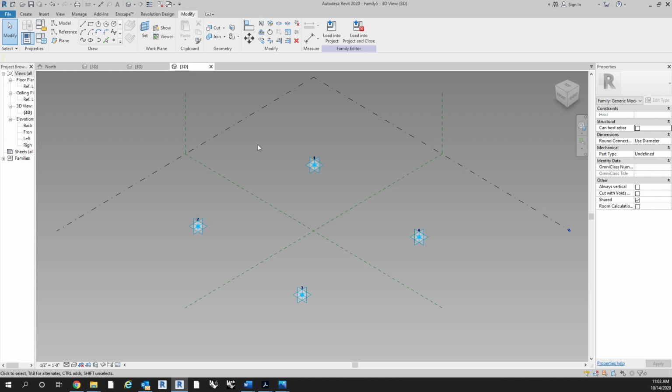The big thing when creating these panels is using the spline through points tool to make sure that the line work we're creating, and subsequently the geometric forms we're creating from those lines, are tied to the adaptive nodes, which are hosted to the surfaces, which manipulate themselves to the curvature or geometry of that surface.